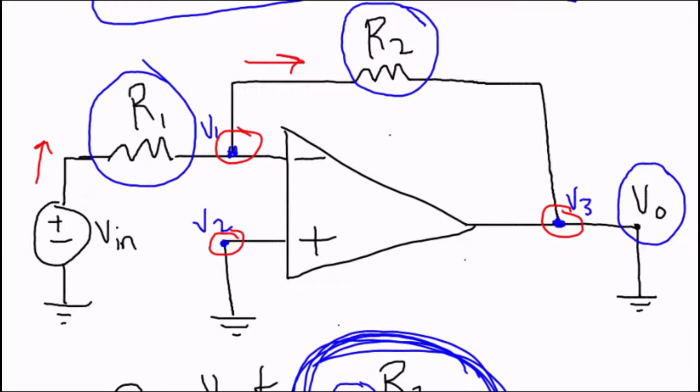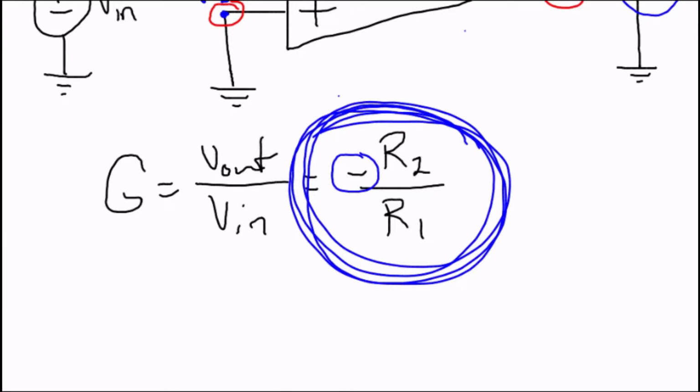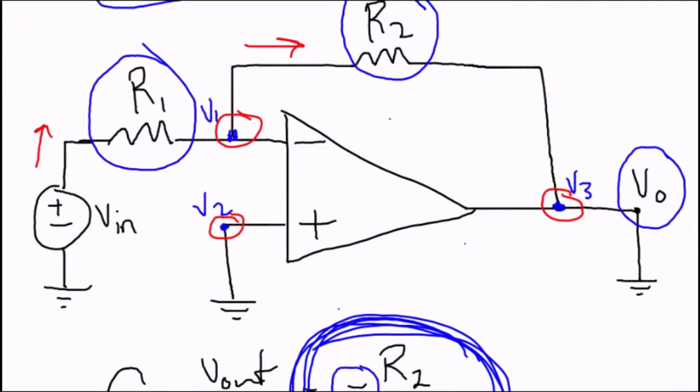It's got zero output impedance, which means there's no voltage drop from Vout to ground. It's got an infinite open loop gain, which means that the difference between V1 and V2 is nothing. If we have an infinite open loop gain, the difference is nothing, which is very, very important in finding this gain value that we've got on our whiteboard, because it allows us to apply what we call a virtual short, which essentially results in this on our whiteboard. So the voltage between this point and this point, the potential difference, is nothing. And that's very important to get there as well.